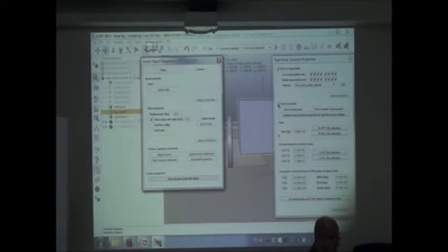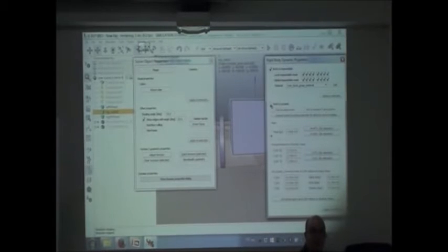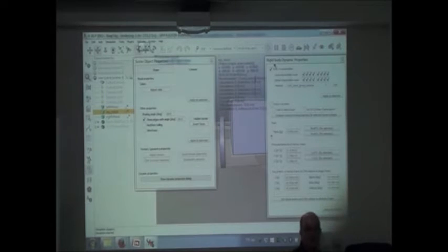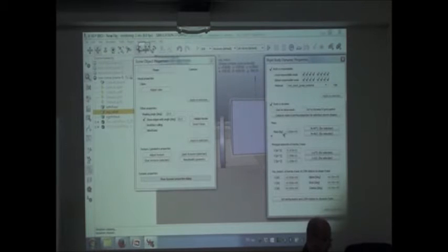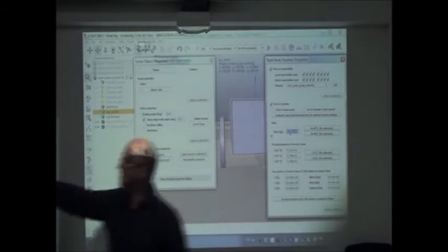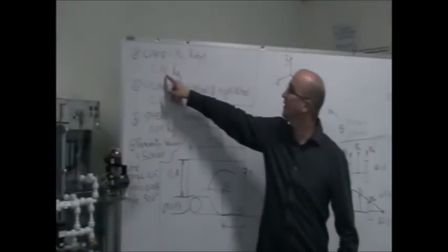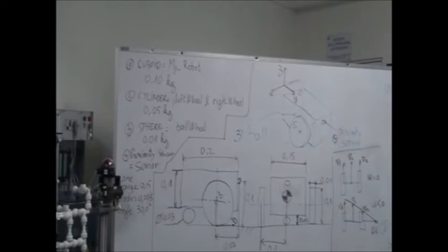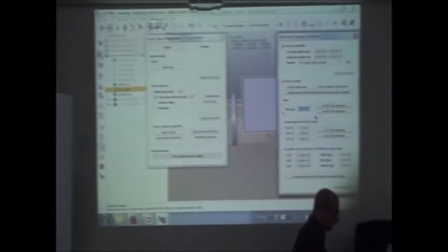If I click here, the robot will not be dynamic. It means that if I press play, nothing happens. It will not fall because it's not a dynamic object. It's just an object that is there. So we want that to be a dynamic object, and the weight is 3 kilos. This is a small robot, it might be way less. Actually, I want the cube, my robot, to weigh 0.1 kilo, 100 grams. This is barely more than enough. So let's change it and put 0.1 here.